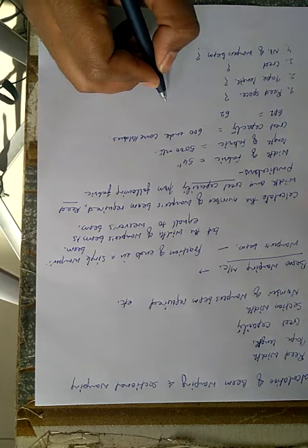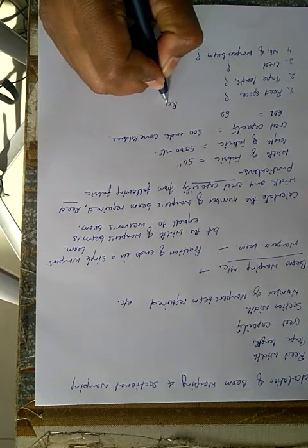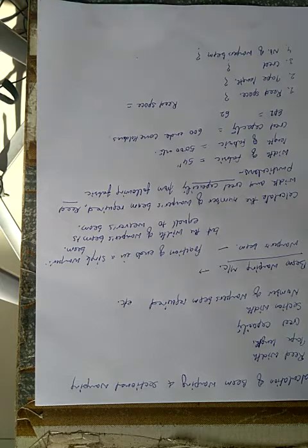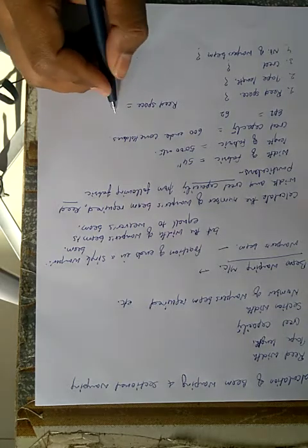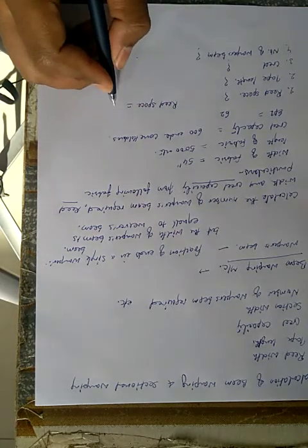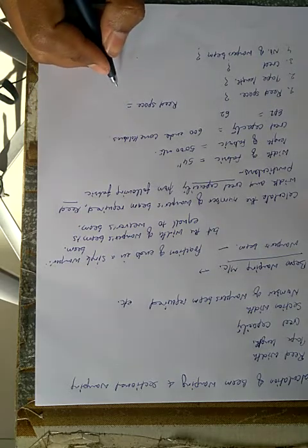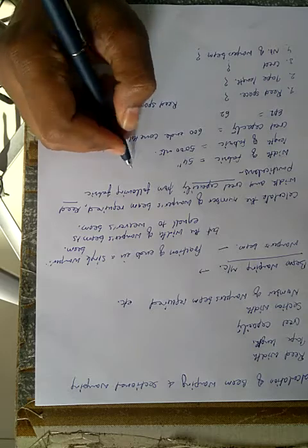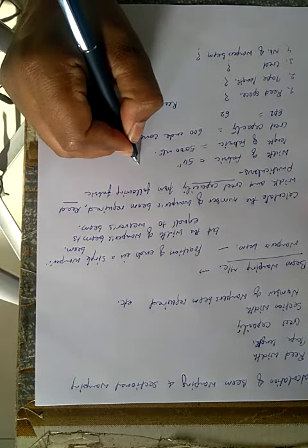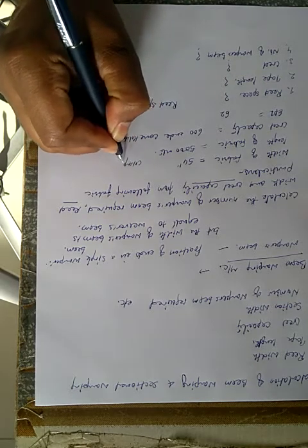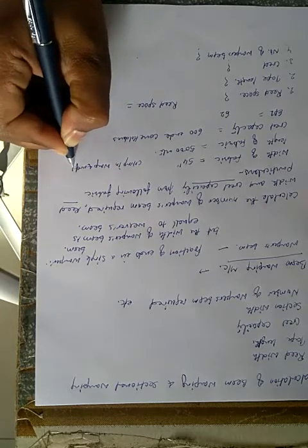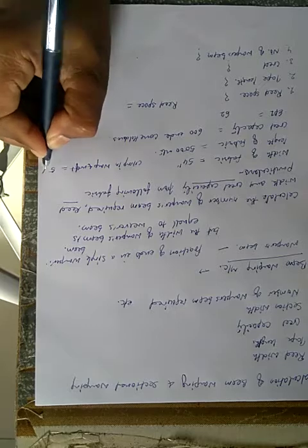So as you all know, reed space or reed width we can calculate by adding crimp in the fabric width. Here we can assume that the crimp in warp and weft is 5%.